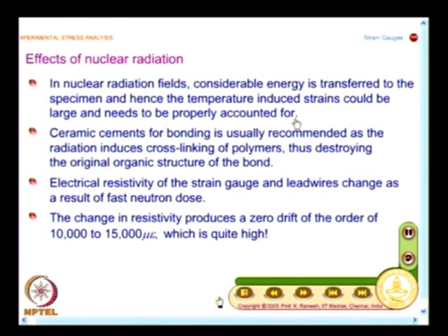See, we have earlier looked at how to accommodate small temperature changes. Here it does not come under small temperature changes category, you have large temperature changes possible, and in those occasions the recommendation is measure the temperature at the point of interest. With that data, it is possible for you to go and do some corrective modifications on the strain measured.